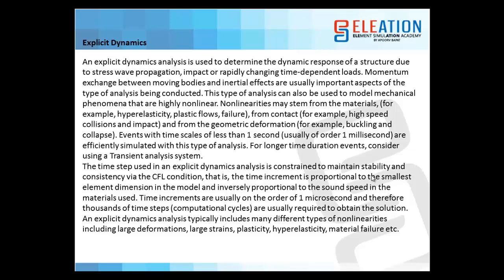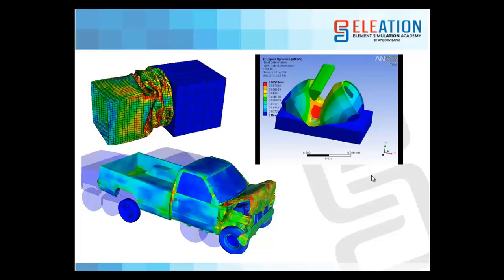An explicit dynamic analysis typically includes many different types of nonlinearities, including large deformation, large strain, plasticity, hyperelasticity, material failure, etc. So you can see these are different examples of dynamic analysis where the deformation is dependent on time.